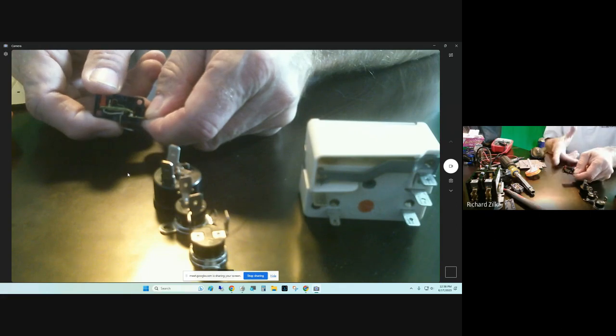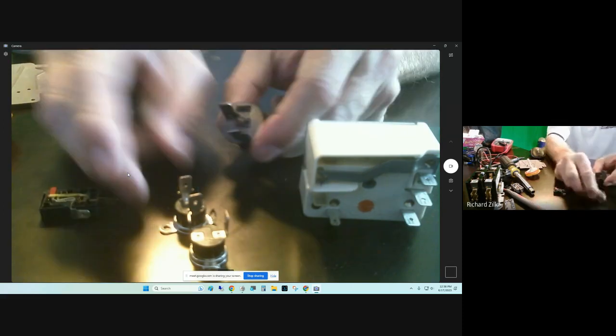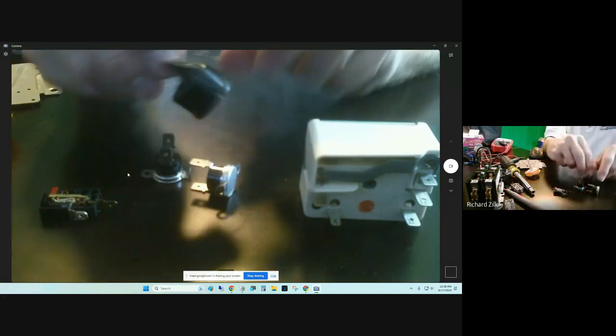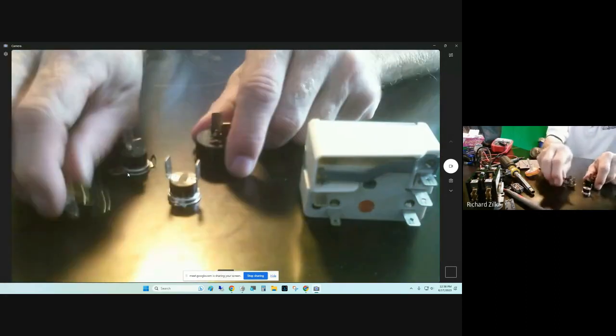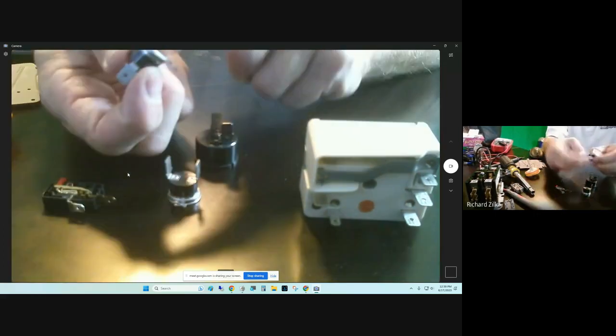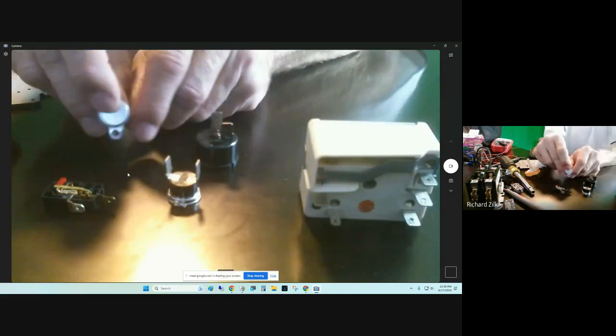And when you open a door, it does that and the microwave stops. So these are thermostats. Or actually, this is an overload for a compressor. But guess what? It's a thermostat. It's a switch just like these switches inside. But when certain heat is applied, a lot of them, I had one of these in my hand to bring to you. I was going to show you inside.